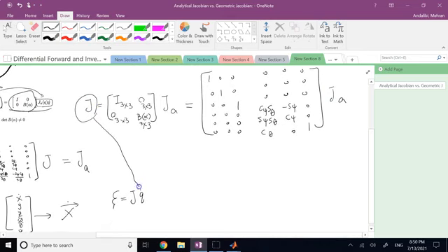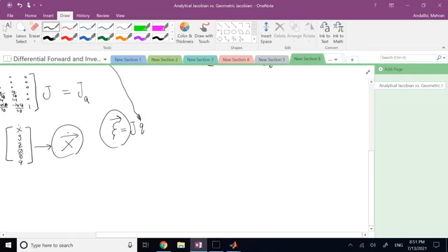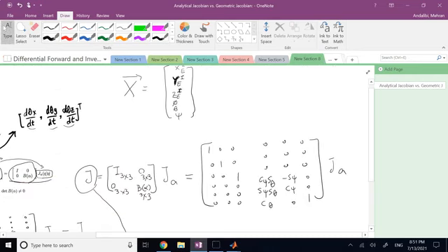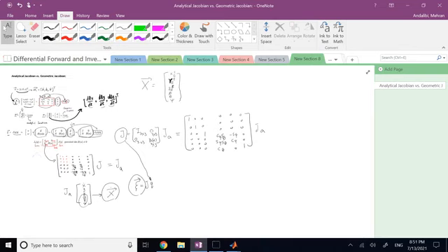and then you can multiply by q dot to give you what? Vector zeta. So depending on what your sensors are giving you, whether the Euler angular velocities or the absolute angular velocities, you can basically use them along with the geometric Jacobian or the analytic Jacobian to get the end effector velocities, okay? So it all depends on what your sensors are returning to you.